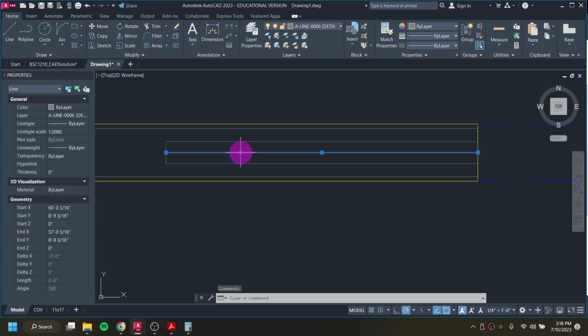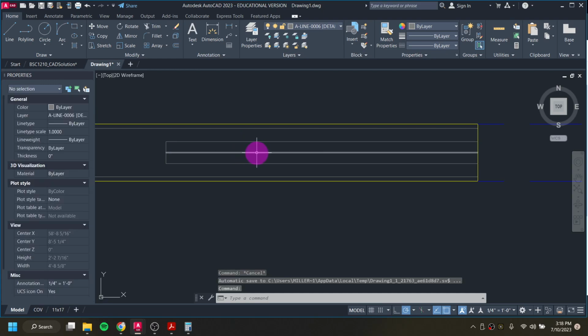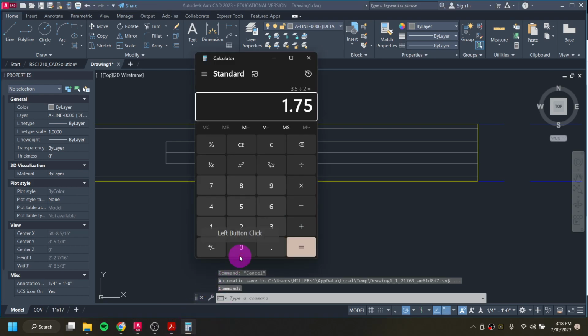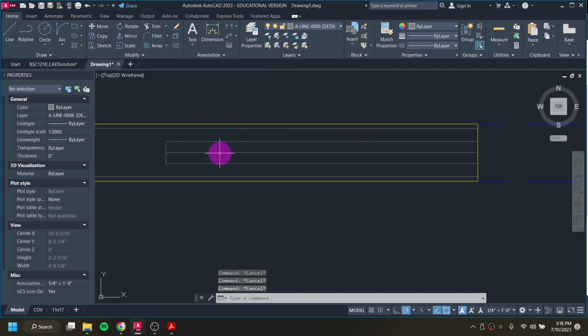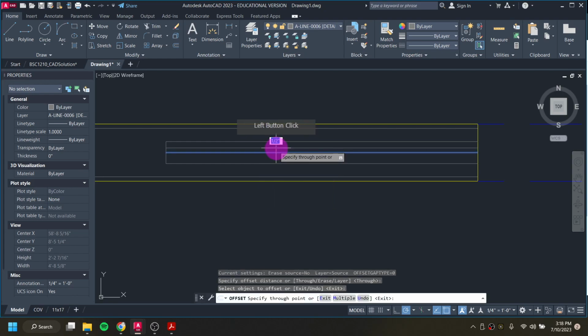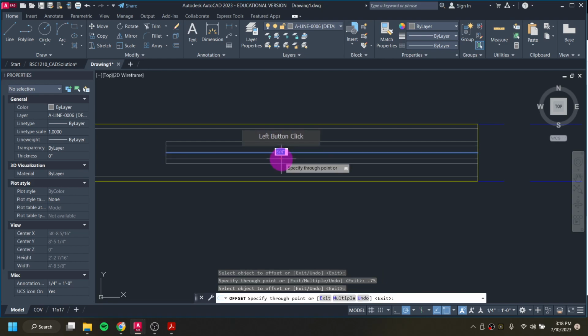I could also then, for my door itself, go and... so that would be 3/4, right? Let me do 2.5, because now I don't trust myself with math. So the door itself is 1.5 inches thick. So then 3/4 up and down for the thickness of the door. I could do offset, enter, enter again to do a through, 3/4 up, 3/4 down. And then this can be the start of the rectangle of my door.